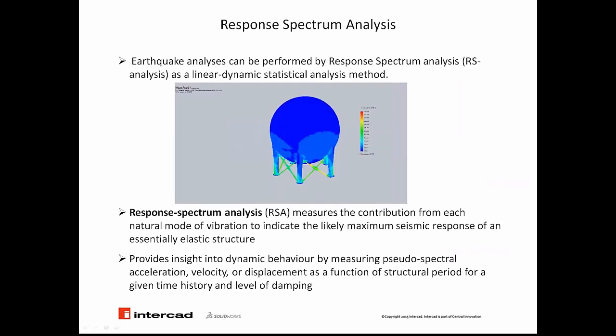Now let's have a closer look at the response spectrum analysis. Earthquake analysis can be performed by response spectrum analysis, or RS analysis, which is a linear dynamic, statistical analysis method. You can see in the picture that you have a base excitation and you would like to measure the contribution from each natural mode of vibration and see the structural seismic response to such a base excitation.